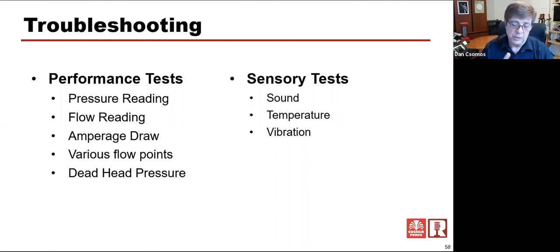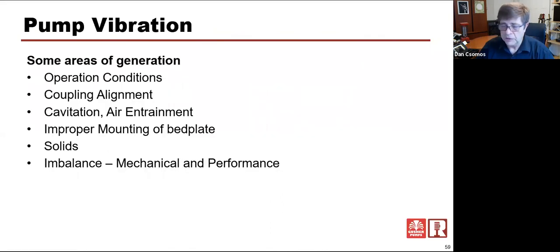But between the combination of the sound, the temperature, the vibration, pressure reading, conversion back to a curve, you can oftentimes tell if a pump is running where you want it to run, or if it's running off the curve. It really helps you define why a pump failure is happening.